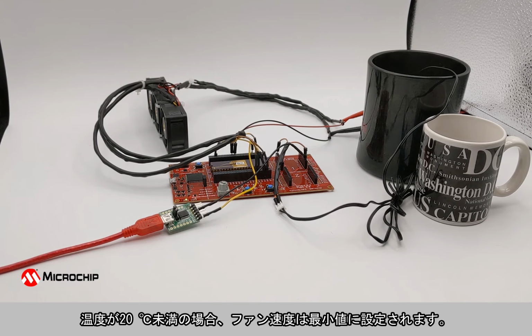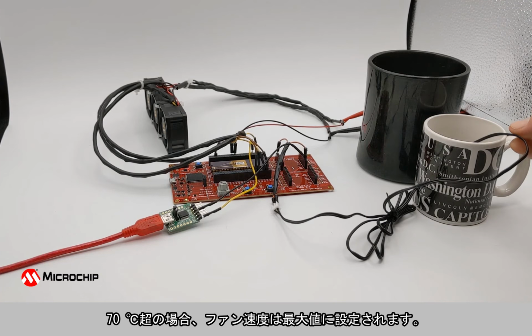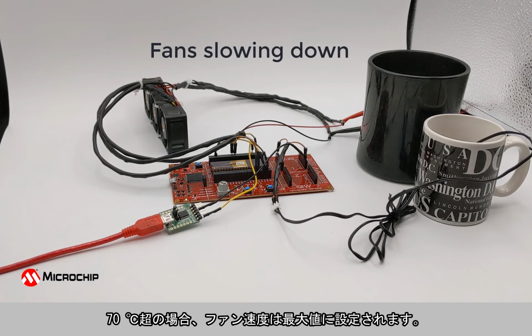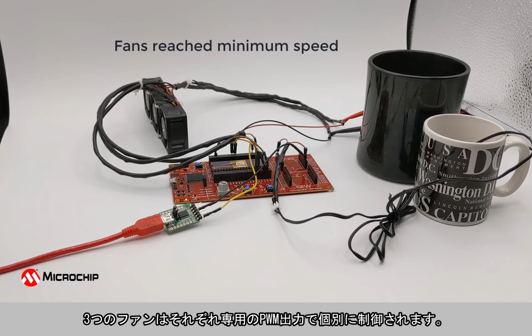If the temperature is below 20 degrees centigrade, the fan speed is set to the minimum value. If the temperature is over 70 degrees centigrade, then the fan speed is set to the maximum speed. Otherwise, the fan speed is determined by the temperature detected by the thermistor. All three fans are controlled individually by their own dedicated PWM output.